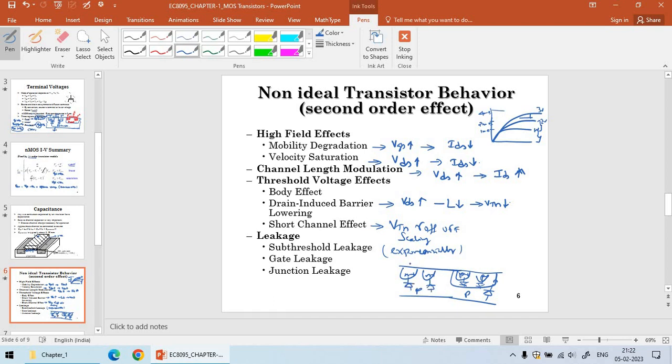So totally 5 parasitic diodes have been created for a chip which contains both NMOS and PMOS. So all these diodes will be reverse biased. There will be leakage when you reverse bias a diode. It is called reverse saturation current.